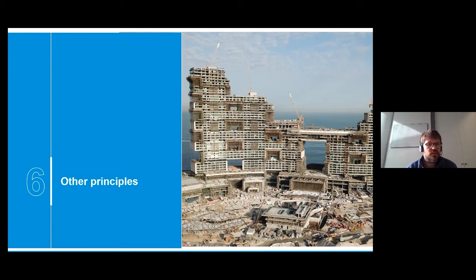If you don't have any reinforcement, usually you don't really need to do anything, because the chlorides are mostly attacking the rebar. Of course, in the standard there is still a limitation. As soon as you are using reinforced concrete, and even worse post-tensioning concrete, then it's really important to verify the chloride content of your concrete. If you have sea sand, you will have chlorides inside your sand for sure. So you have to test it to see the quantity of chloride in the sand. Sometimes, and I already had the case, we tested the sea sand and there was almost nothing of chlorides inside.